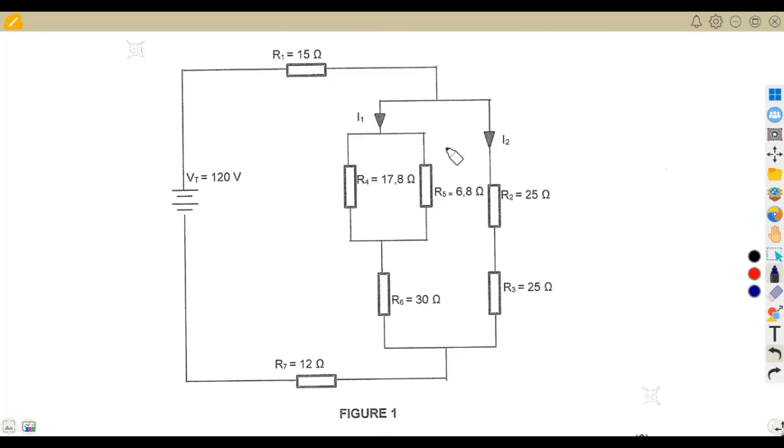If you analyze our DC circuit, you can see we've got our voltage source with the positive, the longer part here, and the negative, meaning the current is flowing this direction. We have the total current of the circuit, which passes through R1. This current from the supply is going to branch. After this, we've got a parallel combination, so our current branches this side and this side.